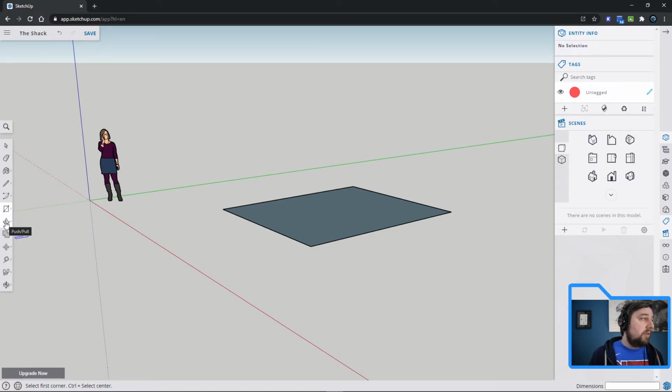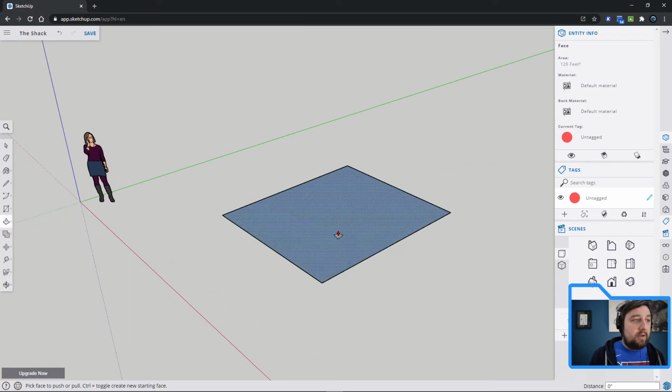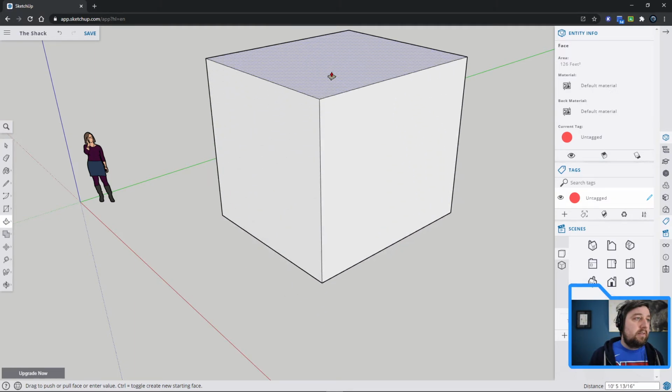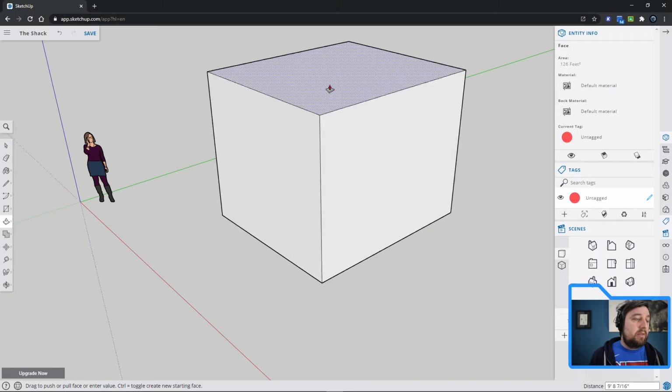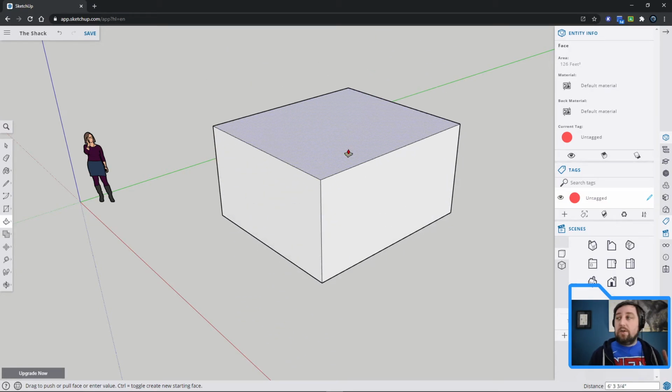I'm going to click on press pull, or push pull, sorry. And now you'll notice the symbol, it's clicked on now. If I mouse over the rectangle I drew before, it starts making these dots on it. All right, if I click on it, and now look, I can start pressing and pulling and making it three-dimensional in the direction of the face that I clicked on. So I can only go up, down.